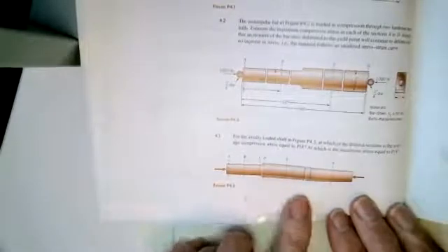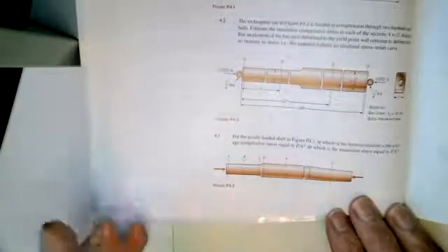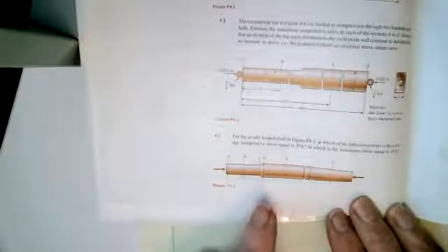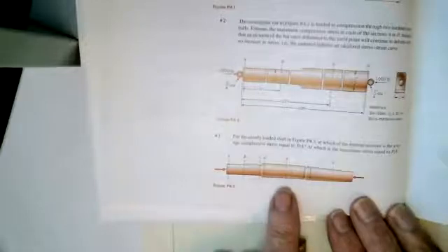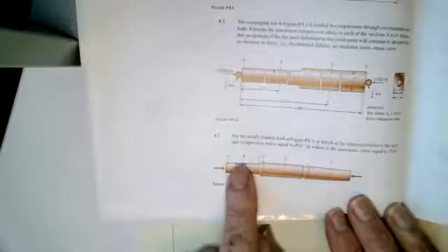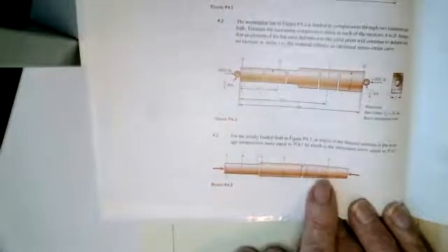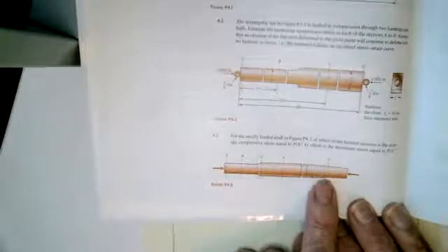This is problem 4.1 here. And I asked the question, at what sections is P upon A the average stress? Well, P upon A is always the average stress, but sometimes there's no disruption to the stress, and so P upon A, the average, is equal to the maximum. So right across here, the stress would be constant. So P would be constant. This is gradually tapering, but it's a very gentle taper. So this would be where the stress all the way across is P upon A.